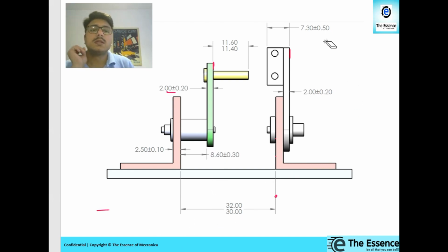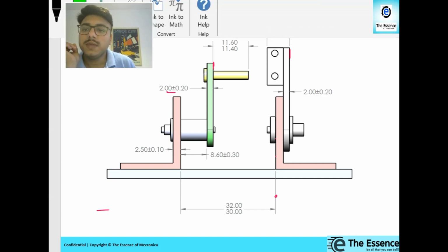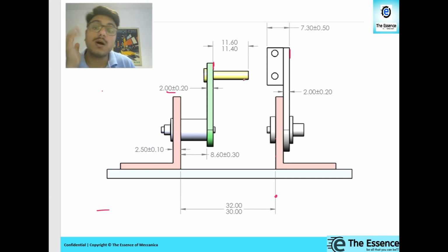Okay. Now we can prepare the loop from the other direction as well, right? I'm interested in finding out this dimension. Now I have started from this side. So I reached this surface because this dimension was there. Then utilizing the thickness, this is A for me. Now this is B for me. Utilizing this thickness, I will go to the back surface of this, that's B. Utilizing the L plate thickness, that's C for me. I will reach its back place.